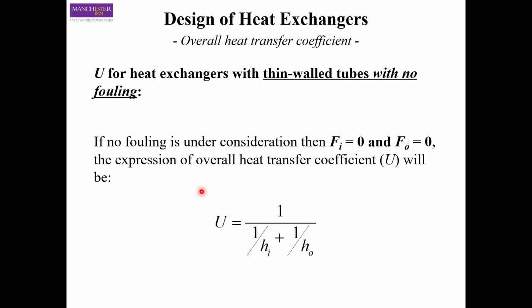So these are the two important equations from this part. One is when we are using U for a clean system without considering the effect of fouling, and the next one is how fouling affects the value of U. So we have to account for these fouling factors.